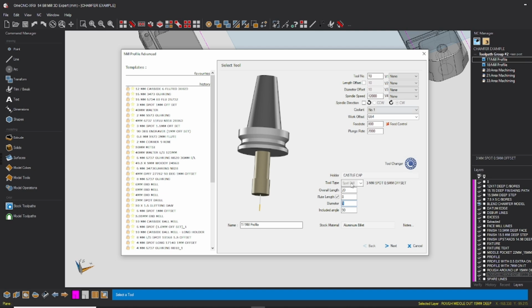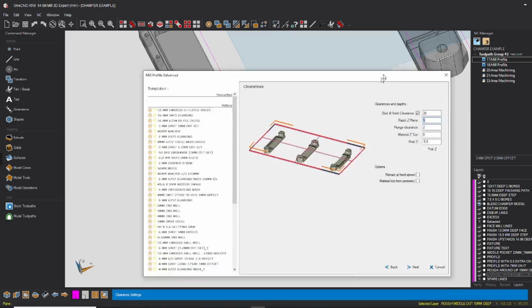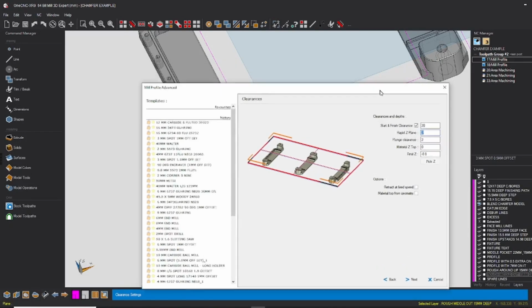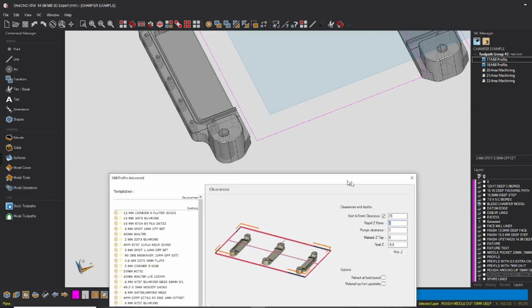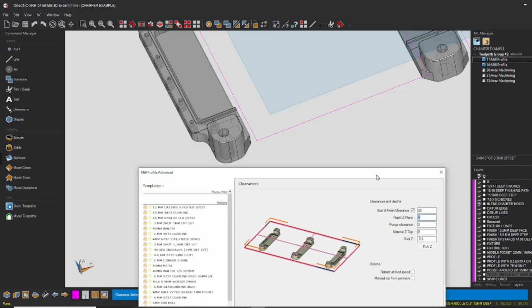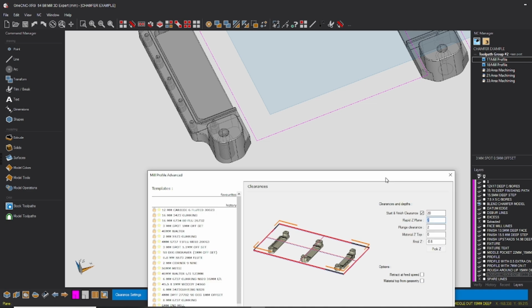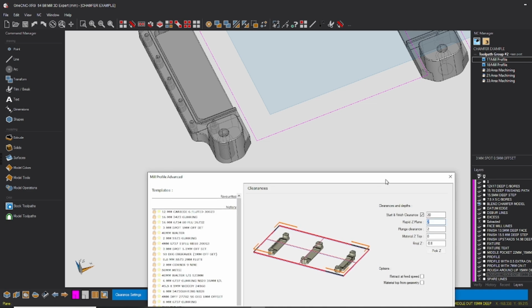So anyway, I set this tool up in my tool library. I just name it 3 mil spot with a 0.5 offset, and then set the diameter to 1. Stick out holder, that's up to you what you have there. And it is a bit notorious with any spot drill, depending on what brand you buy, depending on if you're using high-speed steel, carbide, whatever it is, the quality of them varies, and some of them don't go to an exact point, because obviously if they go to an exact point, that point will be weakened when it comes to centering holes.